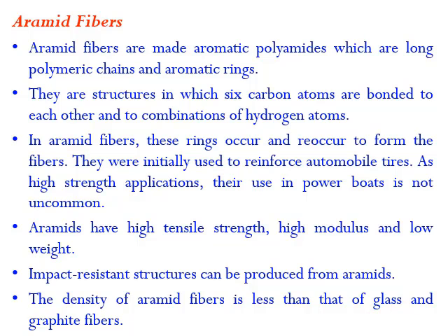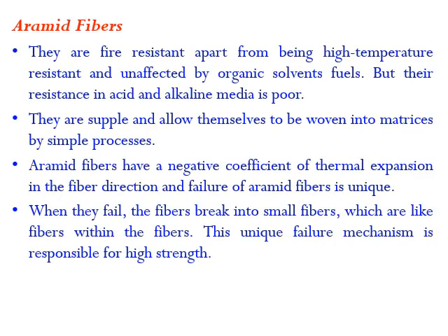So wherever an application needs a light weight and good strength material, we go with aramid fibers. They are fire resistant, apart from being high temperature resistant, and unaffected by organic solvents like fuels. But their resistance in acid and alkaline media is poor. They are supple and allow themselves to be woven into matrices by a simple process, so the processing of these fibers is a bit easier.